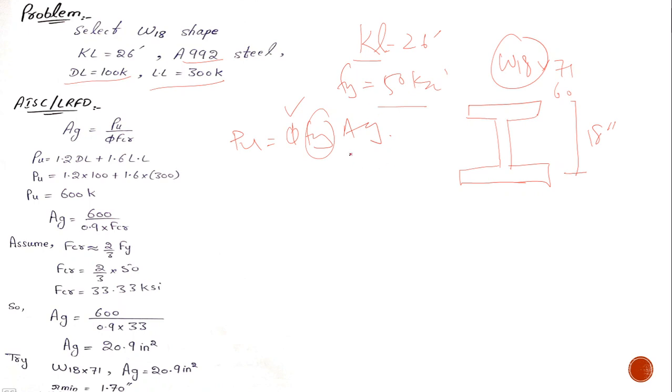Now you know that if a material failure is occurring, then Fy equal to 50 ksi may not be reached. It may fail before 50 ksi. What is material failure? Material failure states that a column never reaches its Fy value. For example, for A992 steel, Fy is 50 ksi, but it may fail before that under loading. So this is a material failure. Okay, what is a geometric failure? The geometric failure says that a material reaches 50 ksi but it may buckle.